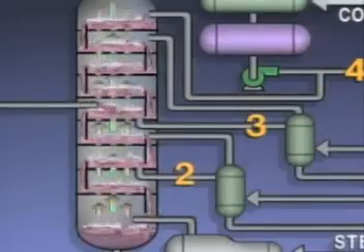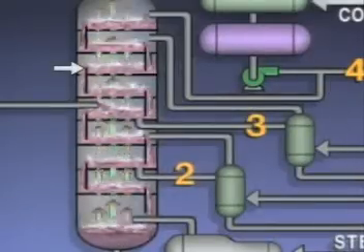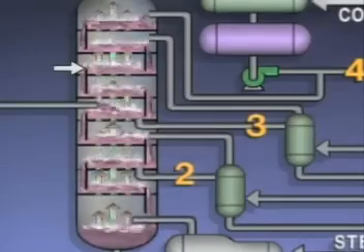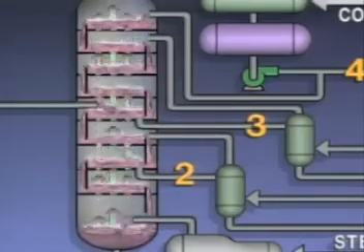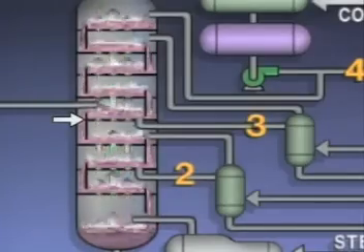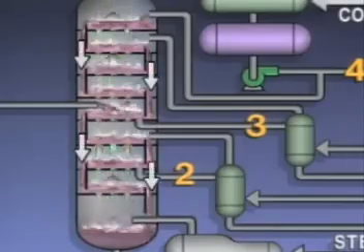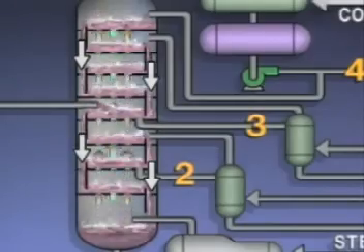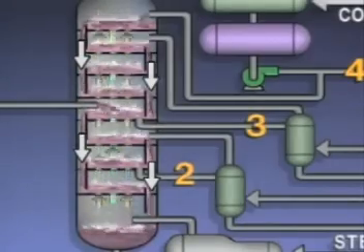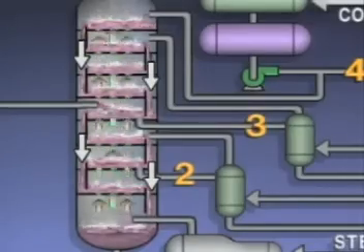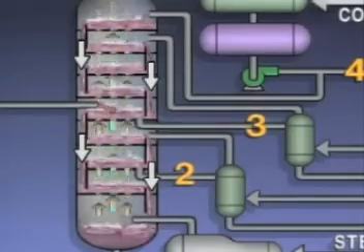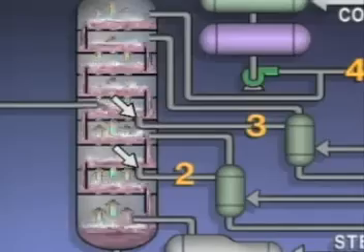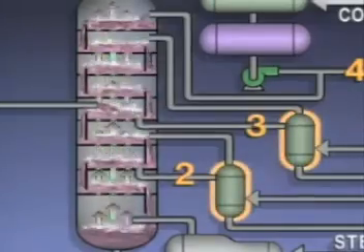The liquid in each tray in the tower collects to the height of a weir, which is a dam-like barrier that holds the liquid on the tray at a specific level. If the tray is at a draw-off point, a portion of the liquid is drawn off through a draw-off line. The liquid overflow from each tray is allowed to flow to lower trays through passages called downcomers. This liquid is called internal reflux. This arrangement helps to ensure that any heavier components of the liquid have a chance to travel down to their proper draw-off points. The liquid that is drawn off by each side draw line goes to a side draw stripper.